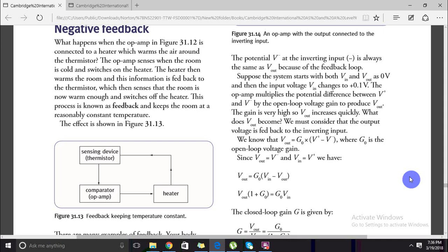And because what we were actually investigating in the first place, what was it that we were investigating? We were investigating the change in G naught. So if this is true, if V out is equal to V minus and V in is equal to V plus, then what is the value of G naught? How do we do that? So what is the value of the actual gain? We are talking about the gain and we're not talking about the open loop voltage gain. So what's going to be the gain? We know the gain is V out over V in. So let's manipulate this in a manner so we get V out over V in.